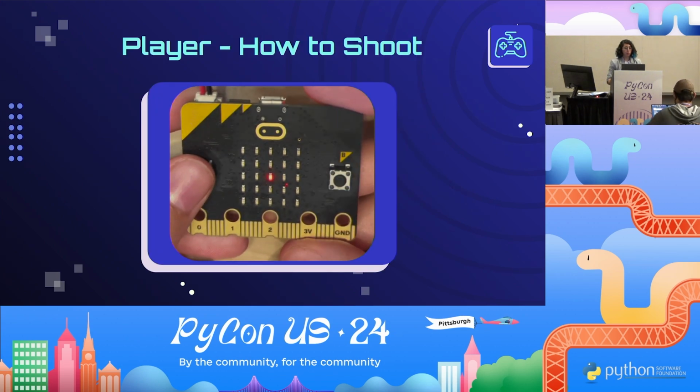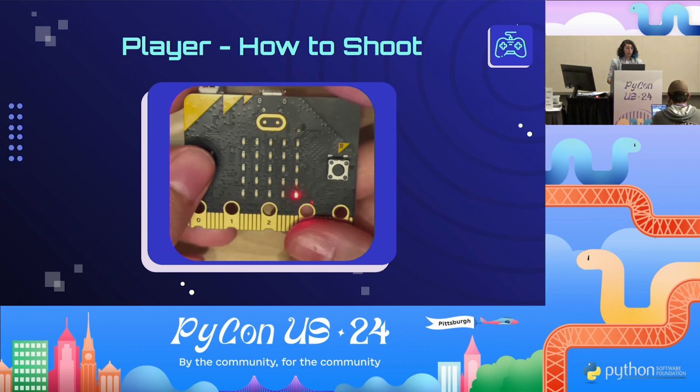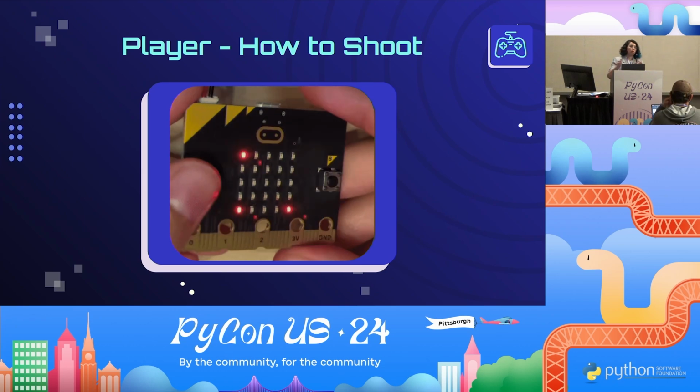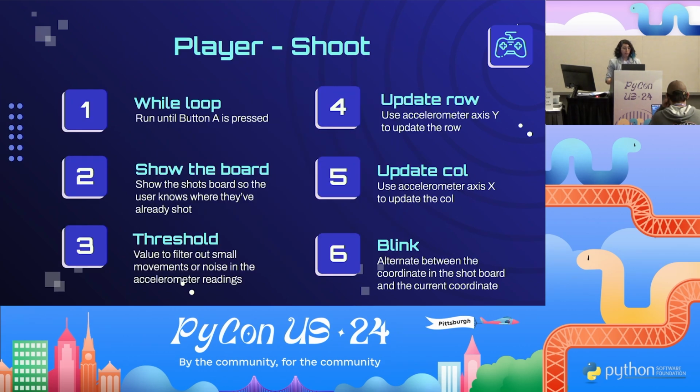So this is how we are going to be shooting. It's similar to the exercise we did, but for this one, since we need more precision, we have a threshold to make it go slower so you don't go all the way to the edge when you turn just a little bit of the board. So how we are going to be doing that? We are going to be looping until we have the button A pressed. We are going to be showing the board so you can know where you have already selected. We are going to have the threshold to filter these small movements from the readings. We are going to be updating the row using the y-axis value, updating the column using the x-axis, and we are going to blink the coordinate and the value that we have on our board so we can see what is happening there.